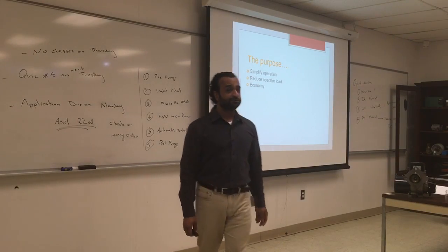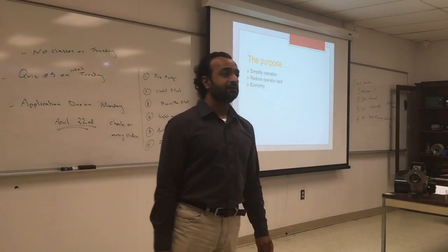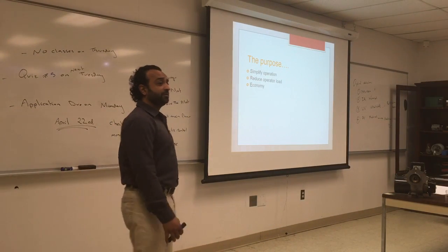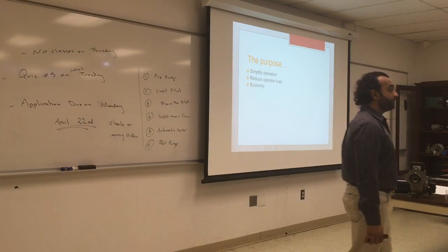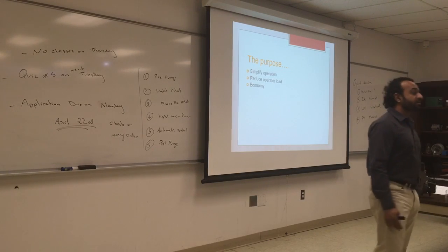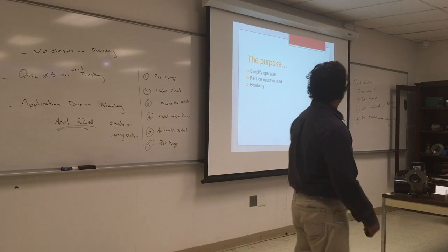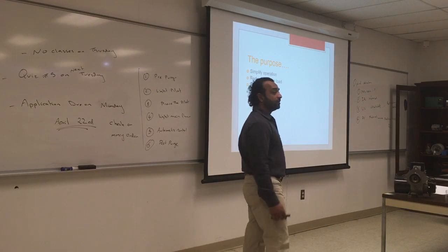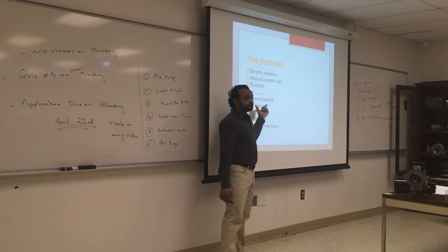If it's more economical to have an automatic control. Why? Because you can gauge the fuel properly based on the load you need. When you drive your car on the highway, they tell you the best way to save gas is to put it in cruise control. No matter how sensitive your foot is to keep the speed at 65, the cruise control will do a better job than you at gauging the fuel and the speed. So the same thing for the power plant. If you want to get a constant firing rate, it's always better for you to have automatic control. Also, steam pressure.